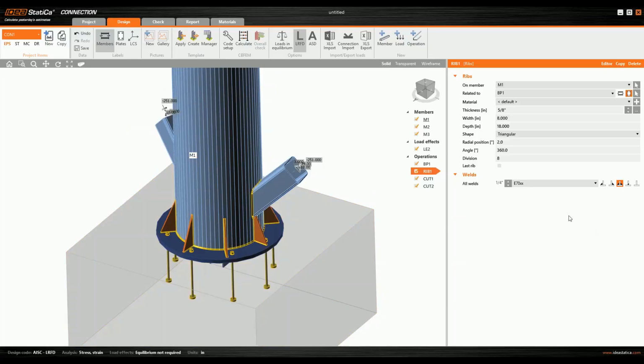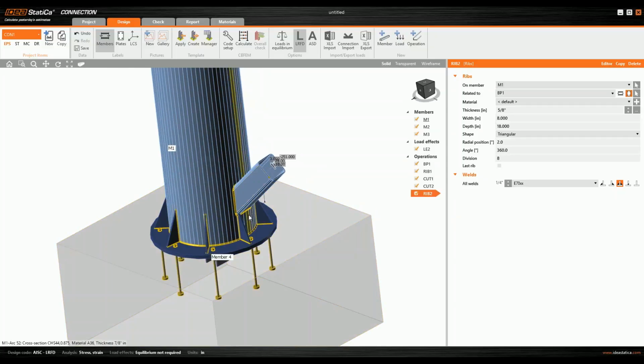Now I add another rib. So I can maybe just copy this one and modify its parameters. And this stays the same. I will add the rib under the diagonals here to stiffen them. So now the size will be 40, and that will be rectangular.